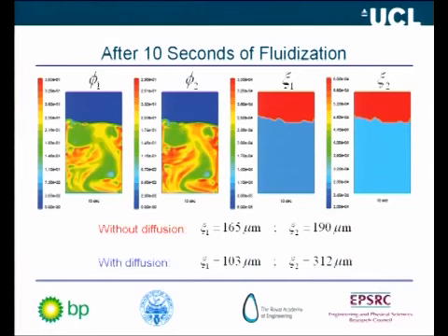After we fluidize the bed, for 10 seconds in this case, on the left-hand side we can see that we are mixing the powder vigorously, whereas on the right-hand side we see how the nodes of the quadrature, basically the sizes, are evolving. After 10 seconds they have already evolved towards some constant values. So everywhere within the domain, the size now is the same. Initially, the bed was segregated and we had 2 different zones with 2 different sizes. Here, the 2 sizes have gone towards constant values.